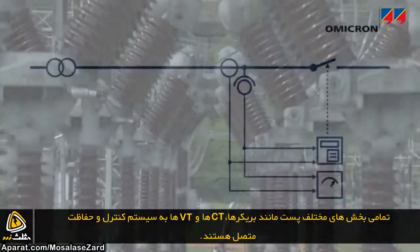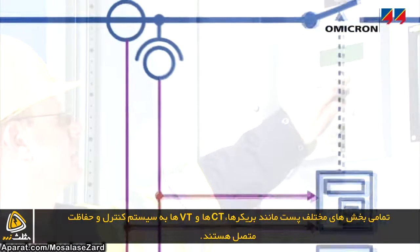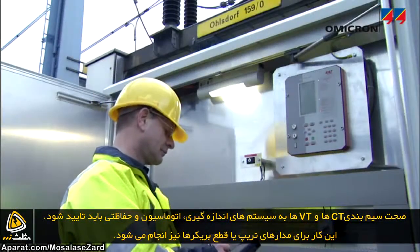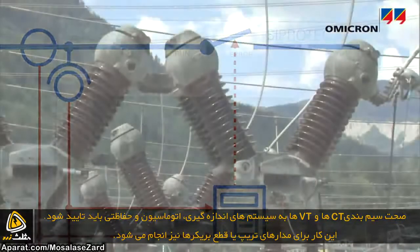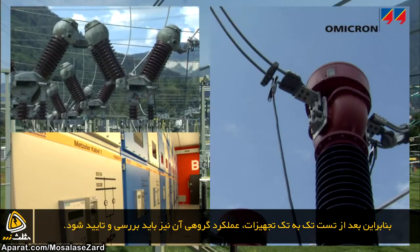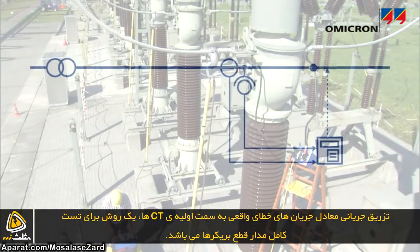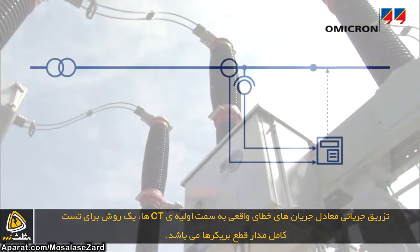All of these substation components, breakers, CTs, and VTs, are connected to the protection and control system. The connections from the CTs and VTs and their individual cores to meters, automation units, and protection relays must be correct, as well as those running from the trip circuits to the circuit breakers. Thus, after testing the individual components, their interactions need to be verified. Injecting current in the range of fault currents into the CT's primary side will cause the protection to trip and allow the whole chain to be verified.